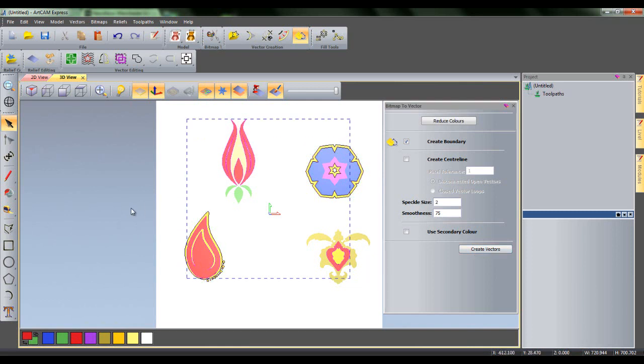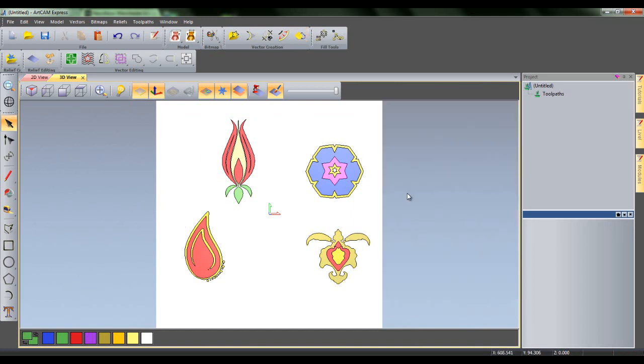However, in the bottom left-hand and the bottom right-hand images, the vector boundaries overlap for these two colors, so duplicate vectors have been created. I must take note of these and delete them where necessary. I can select each boundary which has been duplicated and press Delete on my keyboard to delete them. I will now fast forward to where all my vectors have been created. By this point, you should have created a vector at every boundary between two colors and deleted all duplicates.